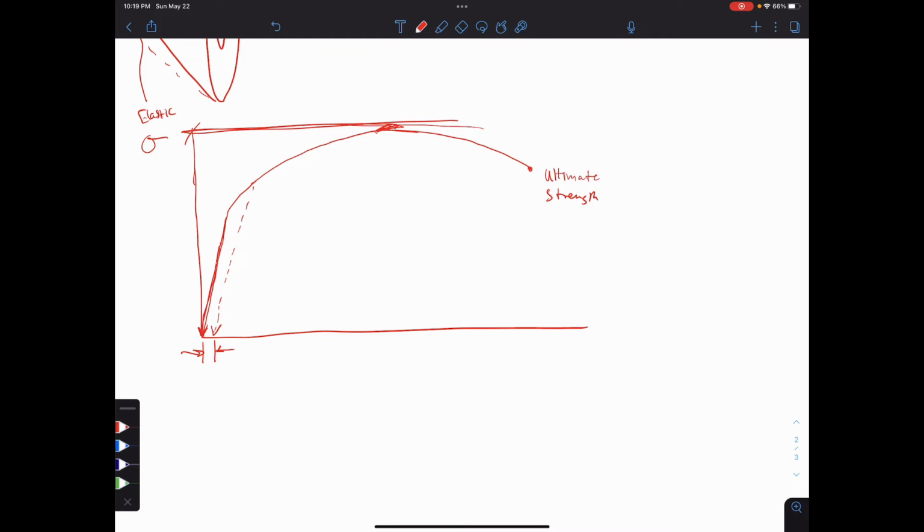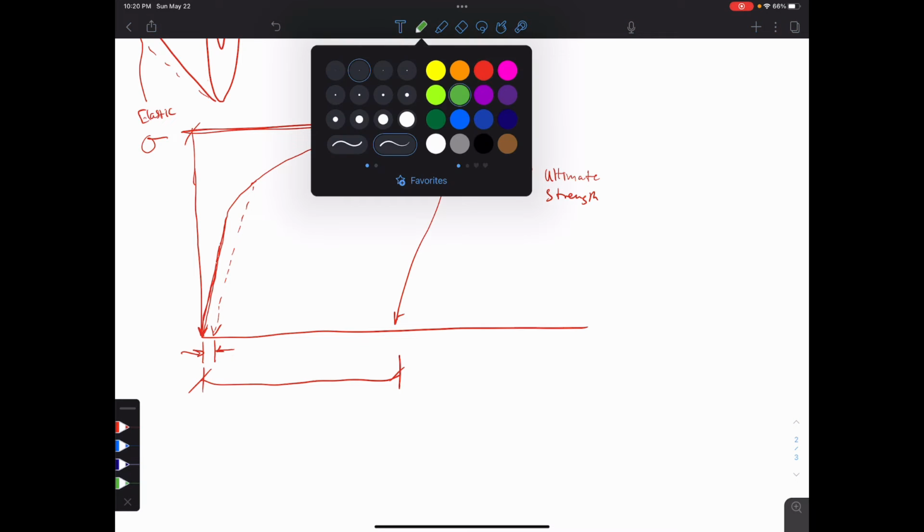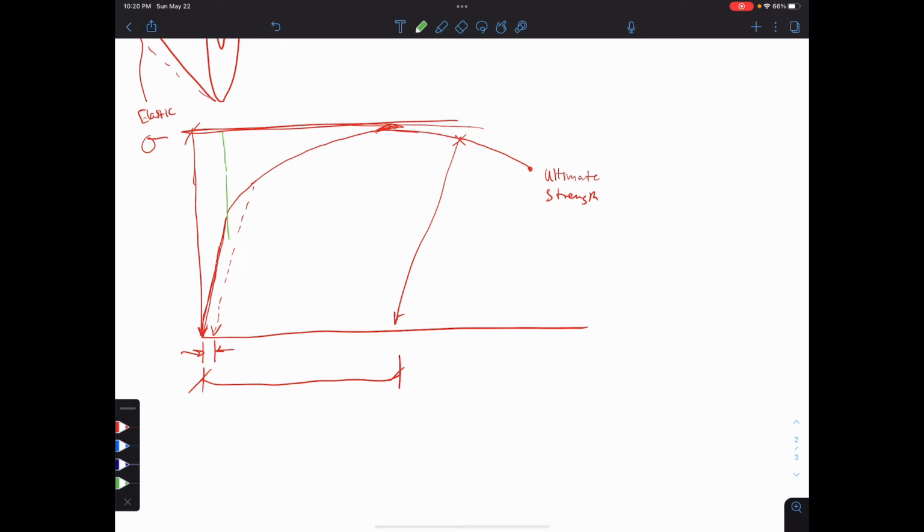But remember, our paperclip is dramatically deformed anytime we're in this region here, right? Because when we let it go, let's say we let go right there, boom, we spring back down here. The paperclip has strained a long way, right? So if we were to label in this graph the elastic region, and then the plastic region, that's how we'd label it, okay?